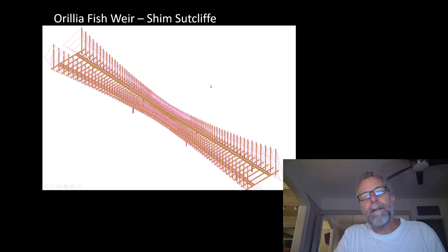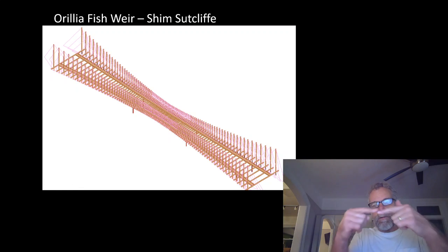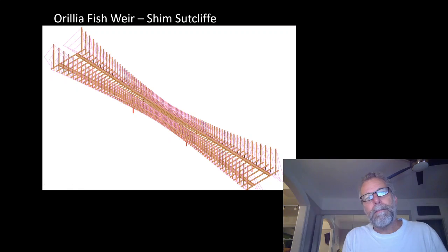This is our structural analysis model, so crudely rendered, but you can see the idea, and you can see that it all ended up working structurally. It worked fairly well. We did wind up needing two very large girders. These were the bottom chord of the truss, for one thing. So the bottom chord is in compression, and these elements needed to carry the compression. But they also serve for erection.